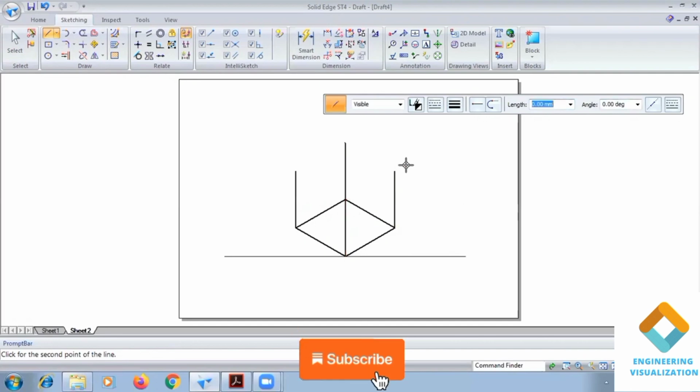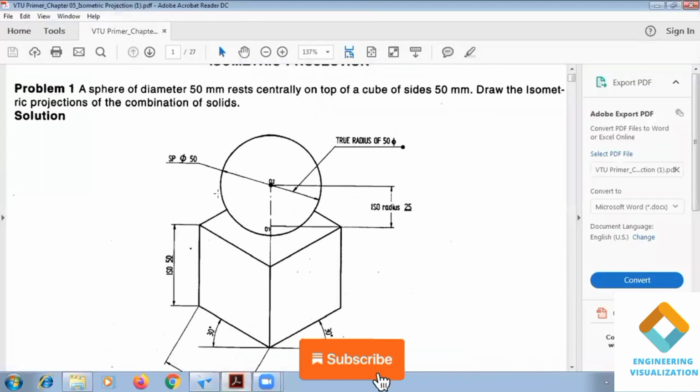Angle is 90 degree. Okay, now construct the top face. So here the cube construction is done, guys. The cube we have constructed. Above it centrally we need to place the sphere here. So that is also having dimension 50.